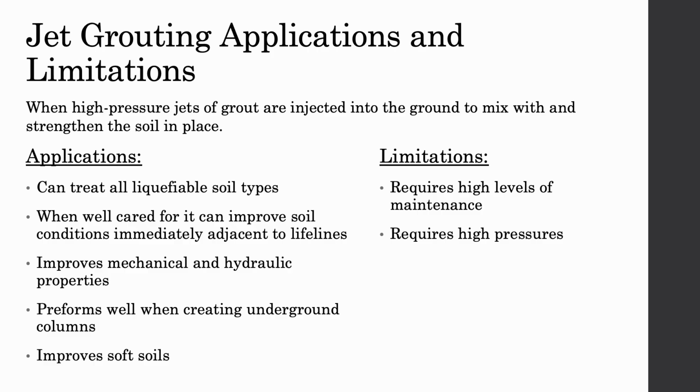Some applications of jet grouting include that it can treat all liquefiable soil types, that when it is well cared for, it can improve soil conditions immediately adjacent to lifelines, that it improves mechanical and hydraulic properties, as well as performs well in creating underground columns and improves soft soils. Some limitations of jet grouting are that it requires high levels of maintenance and requires high pressures.